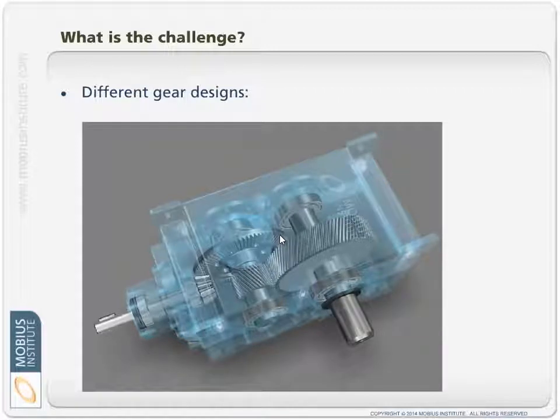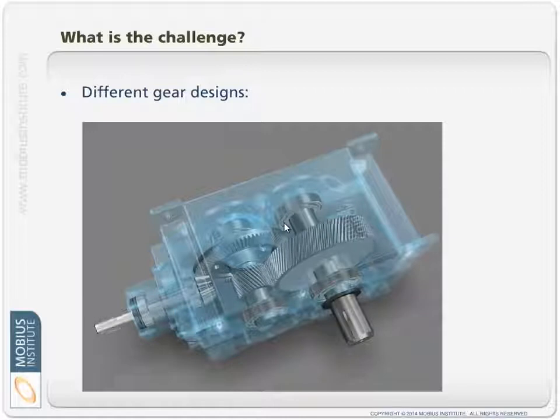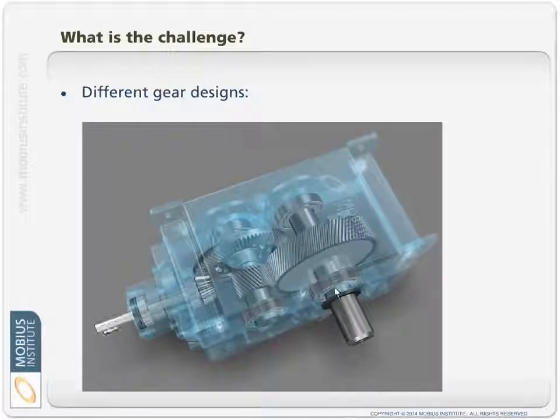Some people actually use the potential of resonance to help them, because they figure, well, if the case resonates, that's going to amplify vibration. That's an interesting approach, as long as you've got good repeatability and a good transmission path from these forces through to the point where you take the measurement.